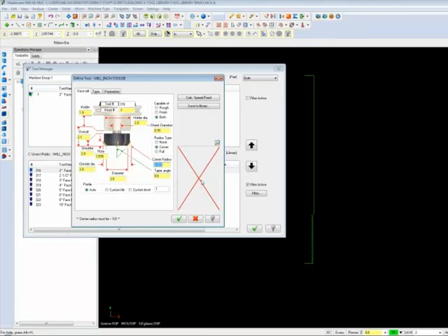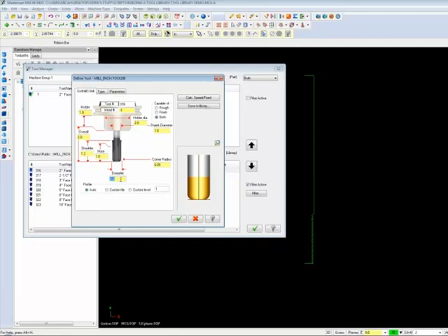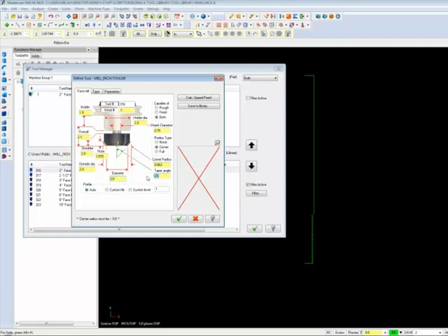So let's go ahead and do that, Micah. Go to your second tab, define it as a bull, and then enter your values there. And visually, you could call it a shell mill if you wanted, and it wouldn't make a difference. Exactly. Now go back to the shell mill and put in 89 and put a radius and see if it works. Yeah, because it's nice to have it say shell mill. Still getting the same error? Yeah.